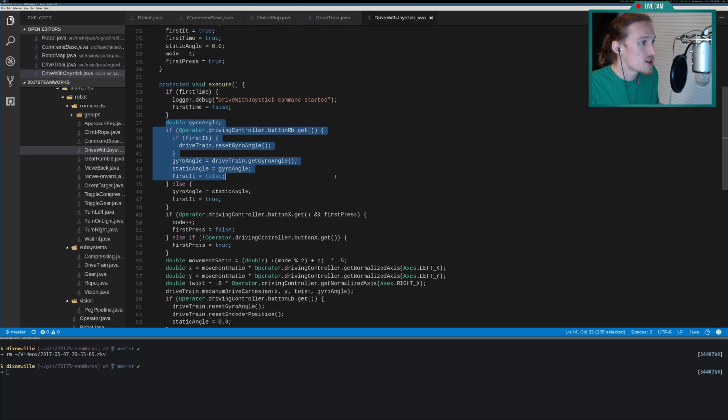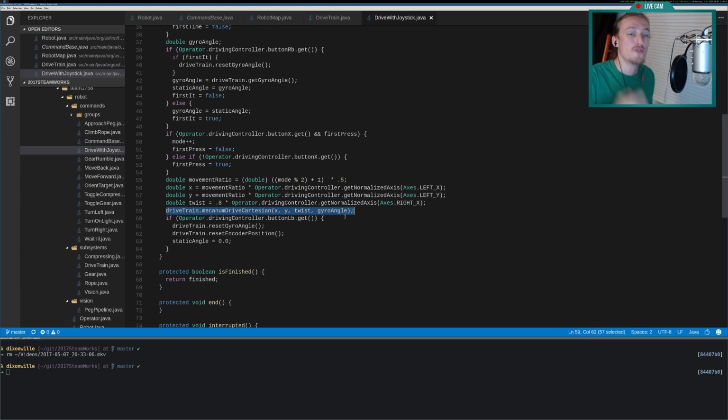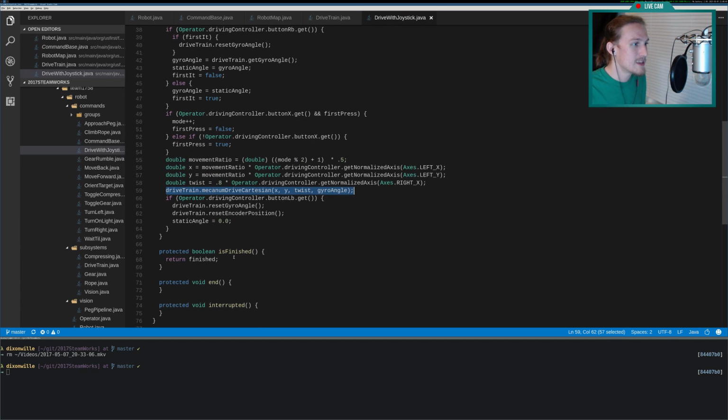Then what we're doing is we're getting certain button values back, doing certain things based on those button values. The main thing that we're doing is taking our controller, setting an X and Y, and then telling our drivetrain, since we used Mechanism this year, to move based on those X and Y coordinates and actually do something. And that's actually what controls the subsystem, these commands. And then whenever you're done with everything, you set the isFinished done. But since this is a command that should always be run, finished is never done because we're in teleop. So, okay. I think that covers the basics of a command.